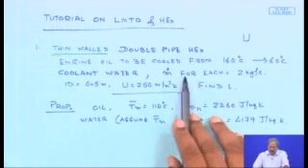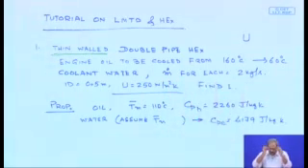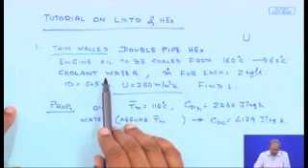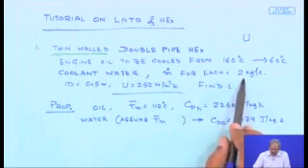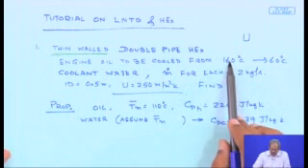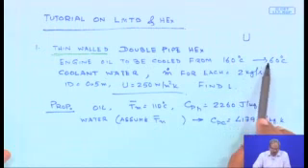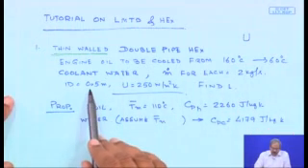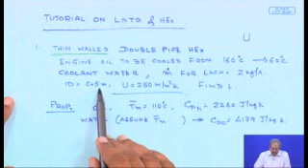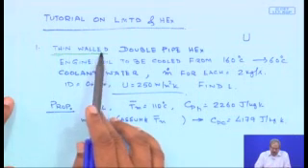So engine oil is to be cooled from a high temperature to a low temperature, and the coolant used is water. If you see the flow rates for each of them, that means for the oil as well as the water, they are provided to be 2 kg per second. The engine oil temperature is to be reduced from 160 to 60. The ID is 0.5 meter. The OD is unimportant, as we have mentioned it's thin walled.